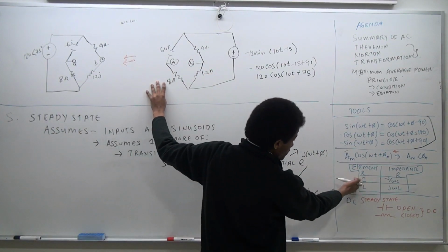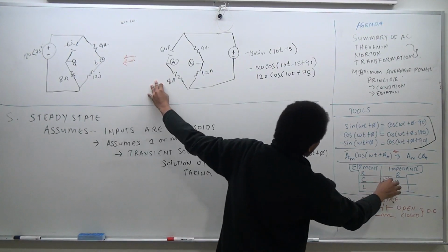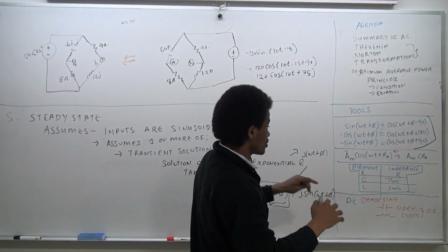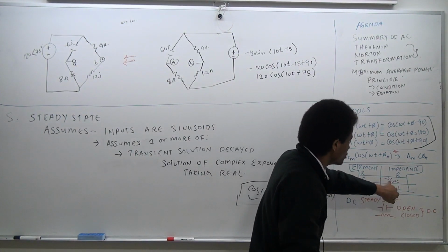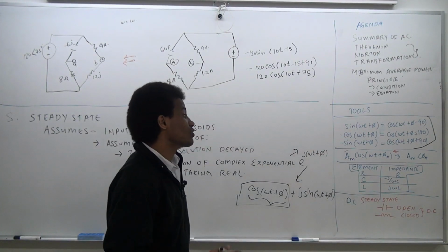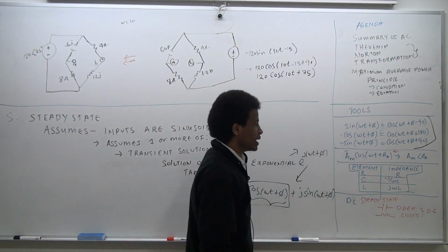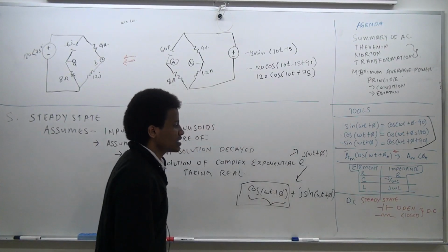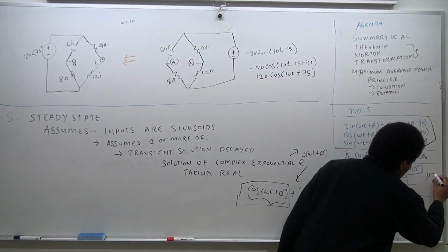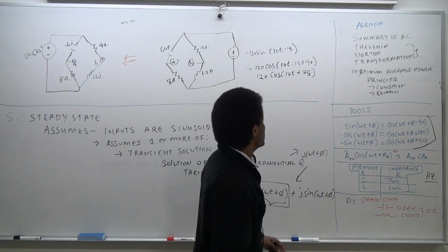For the capacitor, you'll have to do 1 over j omega c. So you will need to know the operating frequency or the excitation of the sinusoid in your circuit. And usually that is captured by the angular frequency omega. Now, sometimes in a problem, they could take it one step further and not provide you with the explicit value of omega. They can tell you that this circuit is operating on the excitation frequency in hertz. They can just give you, for example, something in terms of just hertz. And they're asking you, can you find the impedance in the circuit?